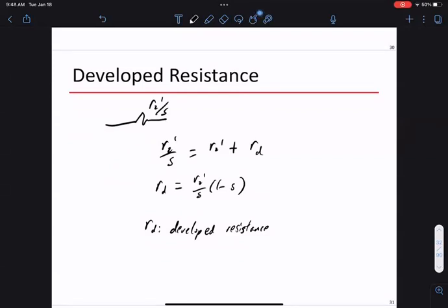Okay, so we have a developed resistance, right? This is developed by slip being negative. And then the calculation is actually quite easy once you get to the circuit. Okay, you compute your speed, you compute a synchronous speed, you get a slip. And you shove that into all these equations to compute the voltage and current, and you can compute the power. Okay, so cranking this equation through is fairly simple to do.